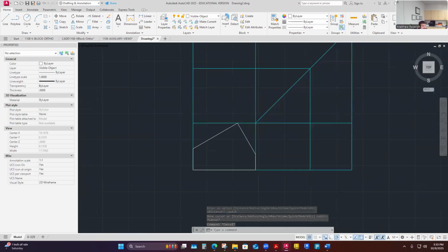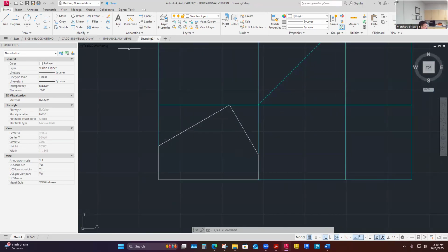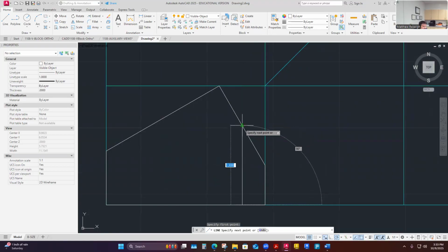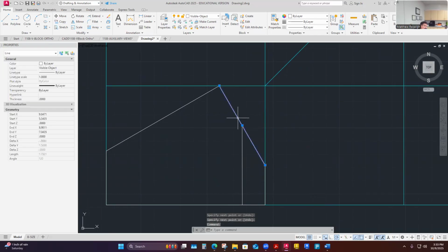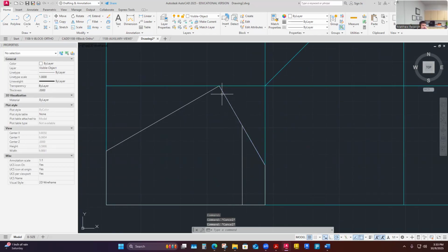And then I'm trying to decide what else I would see there. Well, from that 2.57 point, which is right here, it would go up in my front view and intersect wherever that is, crossing that plane, that surface that's sloped there from the right side view. This surface. If I make sense out of what I've got, this is the surface right against my eyes, and everything that I see there is actually true lengths. So I've got a lot of true lengths that I can dimension here. From this point down to there, it's foreshortened, right? It's going kind of down and away from me.